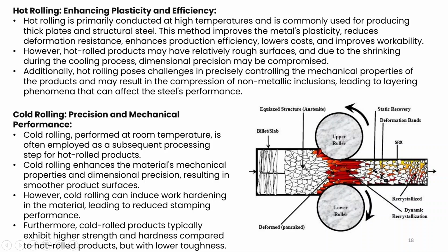So that's why you are getting some dynamic recrystallization. These grains which are elongated will turn into equiaxed grains after dynamic recrystallization. So why will recrystallization occur? Because you are providing some of the activation energy in the form of plastic deformation. So this will lead to the formation of equiaxed grains as you keep on providing some heat.